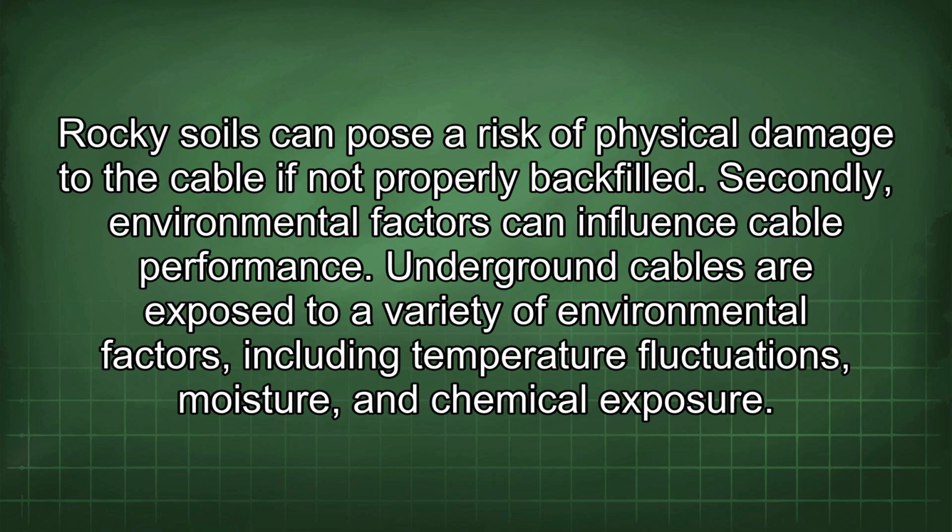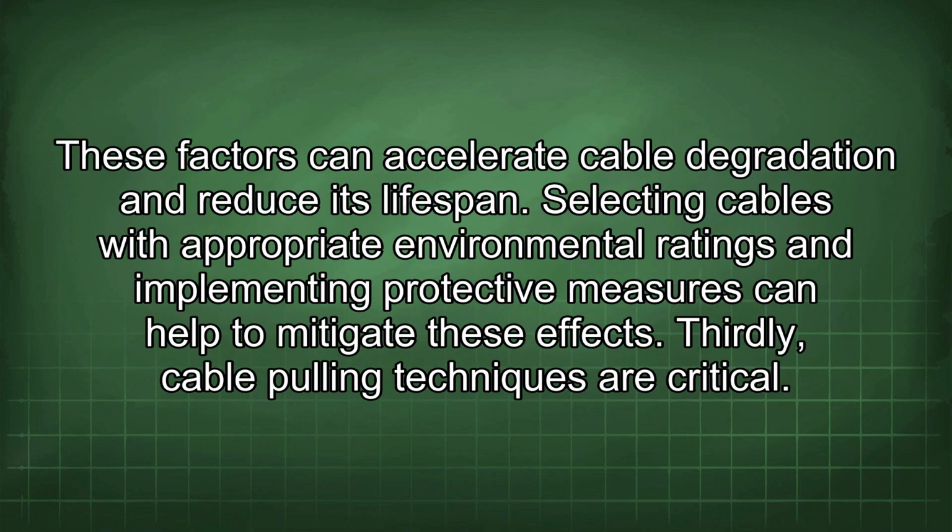Secondly, environmental factors can influence cable performance. Underground cables are exposed to a variety of environmental factors, including temperature fluctuations, moisture, and chemical exposure. These factors can accelerate cable degradation and reduce its lifespan. Selecting cables with appropriate environmental ratings and implementing protective measures can help to mitigate these effects.